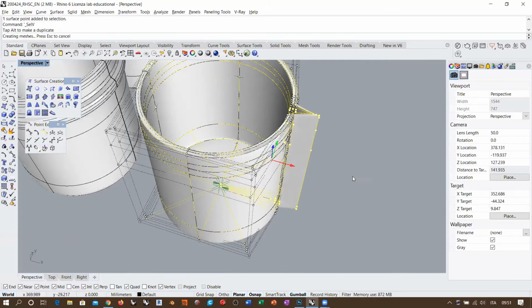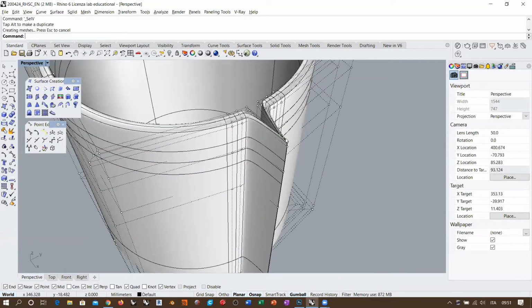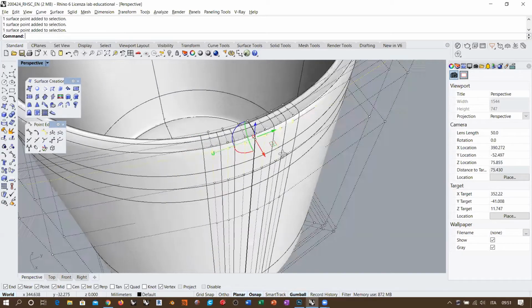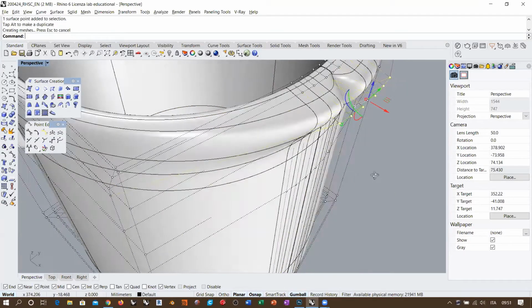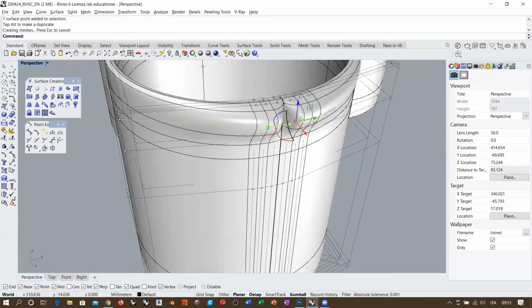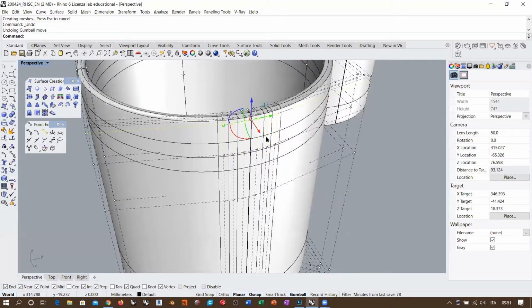So if I move them away, you see that this kink becomes more visible because I have more local deformability due to this amount of control points. But if I don't work with this kink, now I have these points available, okay? And these points on the side, if I try to move these points away, you see that they don't produce discontinuity. They are basically smooth control points, okay? So if I don't break the circle rule around the kink line, I can still create some smooth deformation.